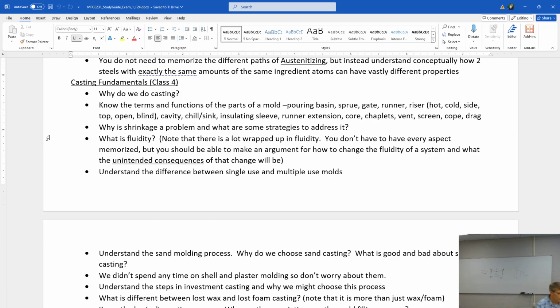To control where the solidification of the casting part starts. Okay, and why does that help us? So it doesn't start crystallizing at the wrong spot, potentially causing the mold not to be filled properly. That's right. If it starts to freeze at the wrong location, then we can't refill the material when it shrinks. So we force it to start at one location and work its way out from there so we can continue to refill from the risers or the sprue as the part shrinks.